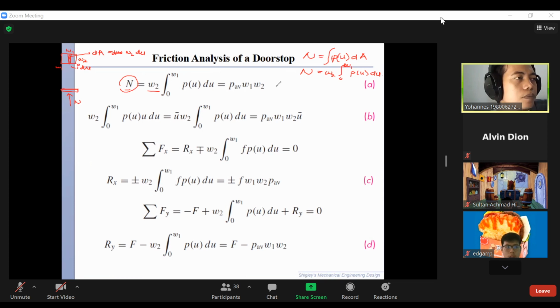And then if we take the average of the force or the pressure, then we just use the average pressure times the area of the brake pad. It means that we avoid the effect of pressure distribution. We assume that the pressure is homogeneously distributed like this. But it is not true. This equation just shows us that we can obtain the average pressure using this equation.